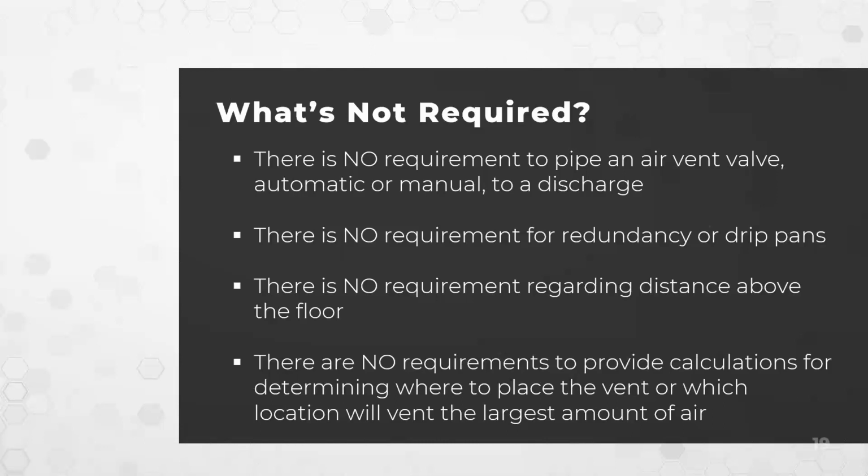And secondly, and this is really due to some marketing efforts of people, you're not required to have any form of redundancy, like one air vent feeding into another. This is really a methodology used by a manufacturer to just sell more air vents. So having one air vent feeding into another air vent, they feel is the best practice. But if you didn't have faith in the first air vent working, why would the exact same air vent in series work any better? So you're not required to have any redundancy in your air vent, nor any type of collection bucket or item around it.